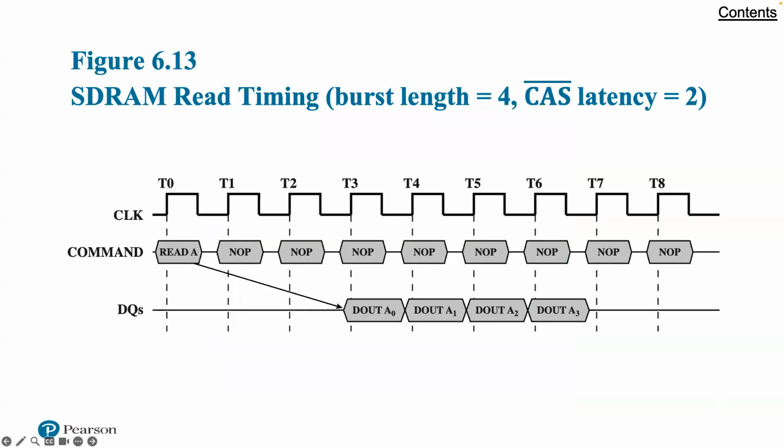So now in this figure, it shows an example SDRAM operation using a timing diagram. So we're going to be thinking about some of the stuff that we just mentioned. And so a timing diagram shows a signal level at a line as a function of time. By convention, the binary 1 signal level is depicted as a higher level than that of a binary 0. Usually binary 0 is the default value. That is, if no data or other signal is being transmitted, then the level on that line is